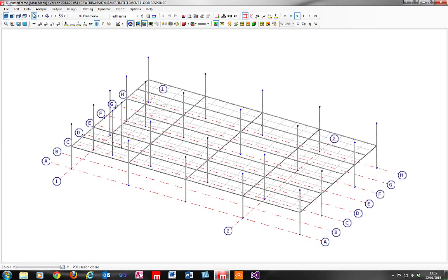Opening up this model, now there's a range of fundamental key differences between this particular model that we've set up for establishing the floor vibration design and what you would typically use for your standard static analysis. In your standard static analysis, you would essentially apply your loading as what we call gravity area loading through the model management tools.